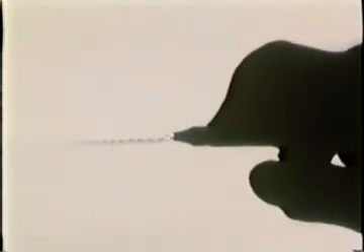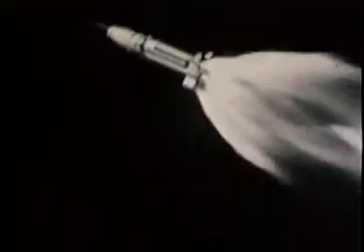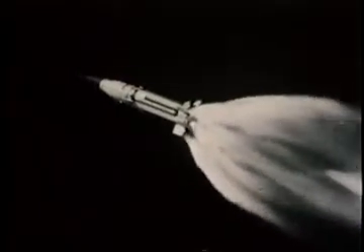This is an ordinary air hose from a machine shop. When we look at the jet with our Schlieren optical system, we find a typical pattern of expansion and compression waves. These waves are the mechanism of adjustment to the ambient pressure. The same pattern can be seen in a rocket exhaust when the outside pressure is not equal to the exit pressure. At very high altitudes, a poor match in pressure is unavoidable. And the expansion wave at a nozzle exit may turn the flow through a spectacular angle.